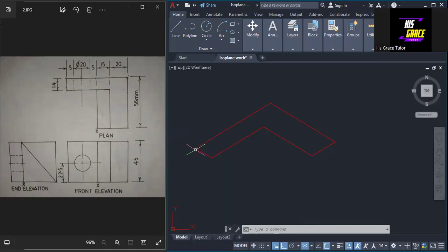You need to make it solid, because from here to here is 45. So we are going to erect a vertical line of length 45 at each of these points. Let me make this shape just one line or one shape, so I'm going to join them together.